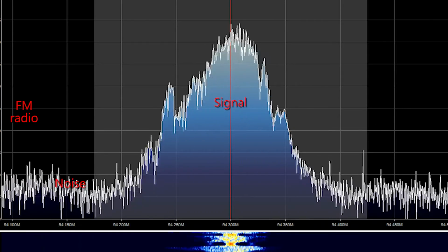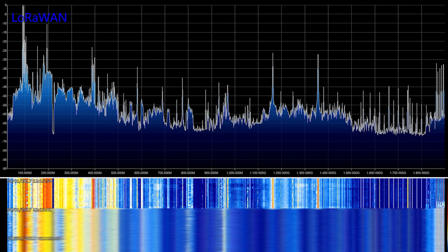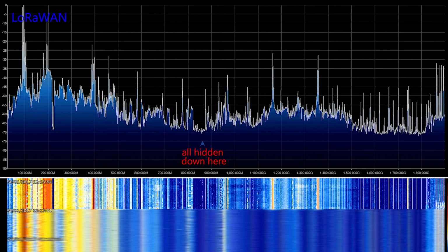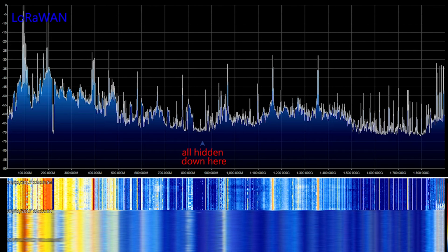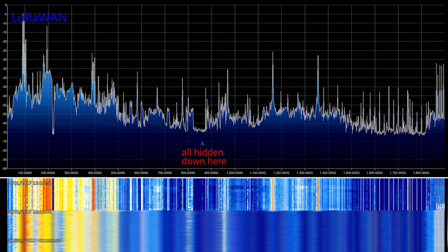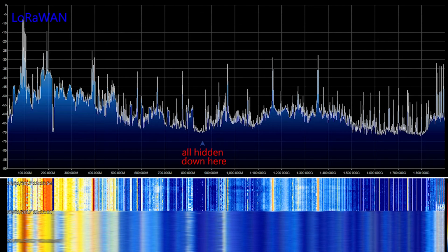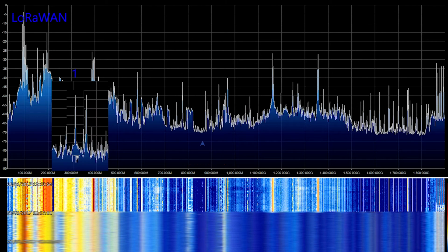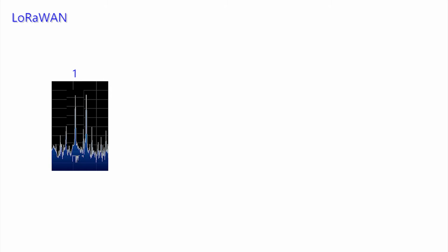It's designed for bandwidth sharing like Bluetooth and Wi-Fi and uses a technique that occupies a wider spread signal. It is at much lower power and can operate quite effectively where the background noise is actually higher than the signal itself. This quite remarkable technique was originally developed for military use, where the intent was to hide the signal. One technique is to use one frequency to transmit a 1 and a second frequency to transmit a 0. This is referred to as frequency shift keying, or FSK. You will see this referred to in the LoRa documentation. LoRa can use this technique for reference, but then goes further, spreading with a more complex signal called chirping.